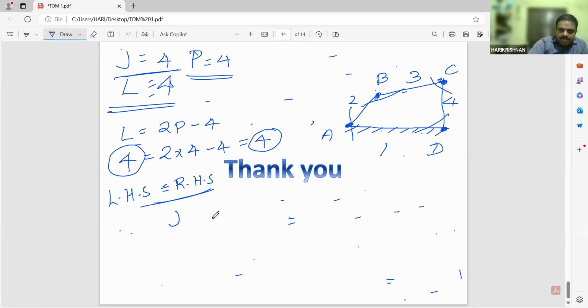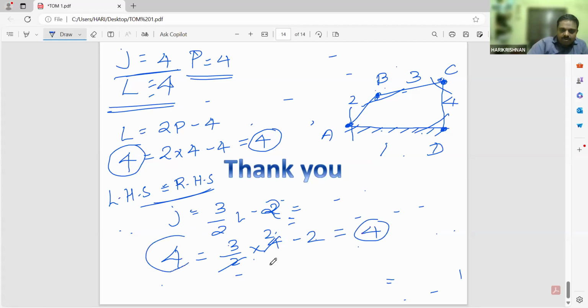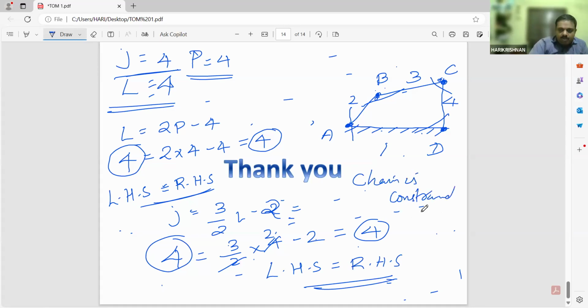Now similarly, J is equal to 3 by 2 L minus 2. The number of joints is 4. 3 by 2 into links, which is 4, minus 2. So the 2 and 2 get cancelled. 3 into 2 is 6, minus 2. The value is 4. So here also RHS is 4 and LHS is 4. So LHS is equal to RHS. When LHS equals RHS, the chain is constrained. Constrained means it has some motion, a constrained motion in one direction or so. So when LHS equals RHS, the chain is constrained.